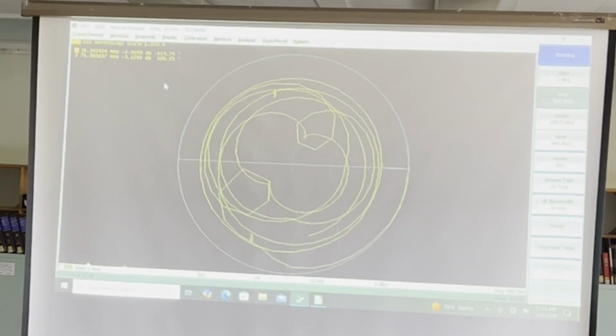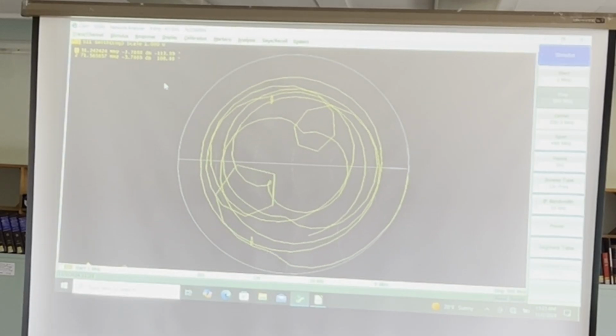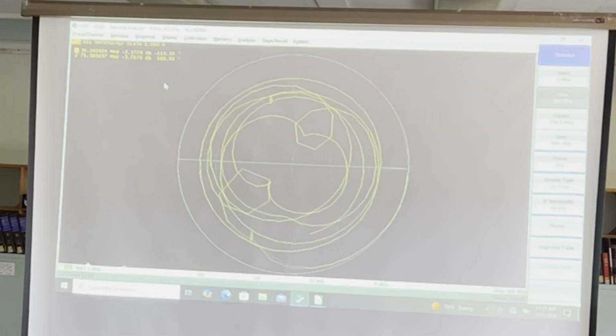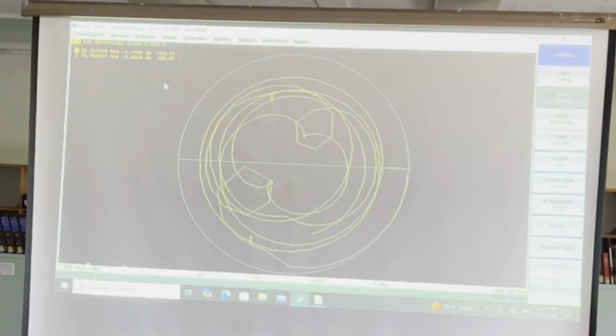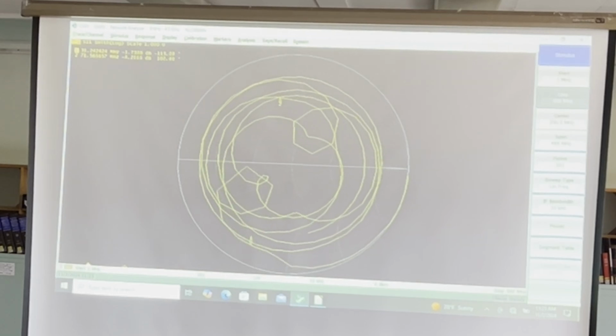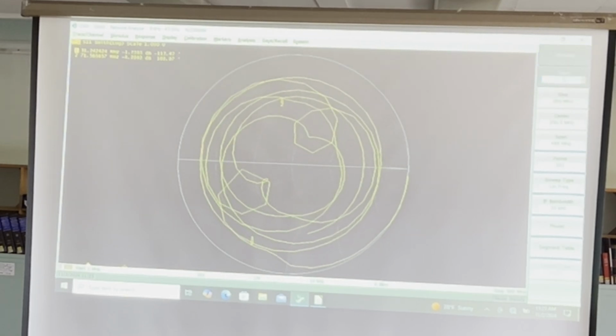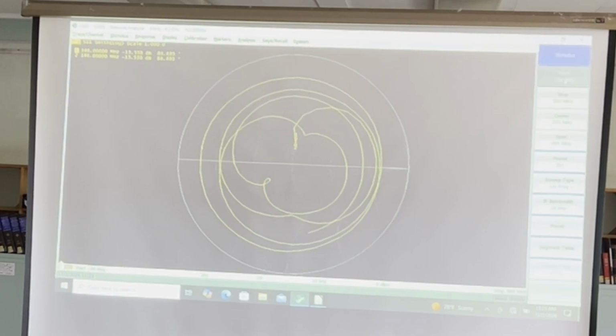But what that's doing, remember, is sweeping from 1 meg to 500 meg. That's just kind of useless. We don't want to do that. We think this is a VHF antenna, so let's go into about 146. Oh, and the picture's getting much better. And let's do 150.